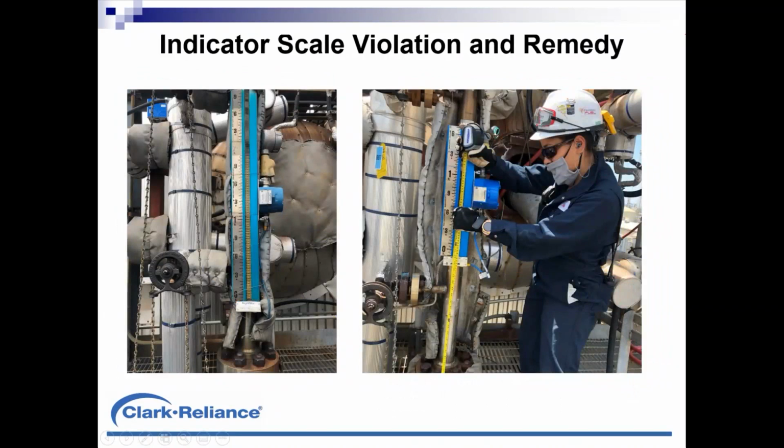Here's a case where a magnetic level gauge was ordered incorrectly by a customer with an inappropriate scale. And you will see this if you look at magnetic level gauges by an assortment of manufacturers. It's not uncommon for scales to encroach into the design connections, but you have to keep in mind, if it's a fluid like a static tank, not even under pressure, it may cause no harm, no foul. However, if we're on a boiler water or a supporting vessel, you can appreciate what could go wrong. And here we have a technician replacing the scale to make this installation code correct.